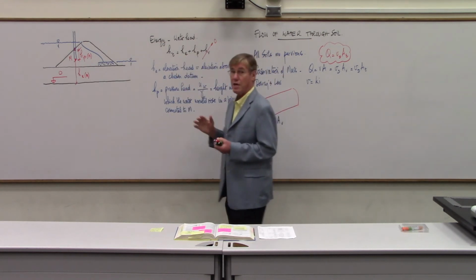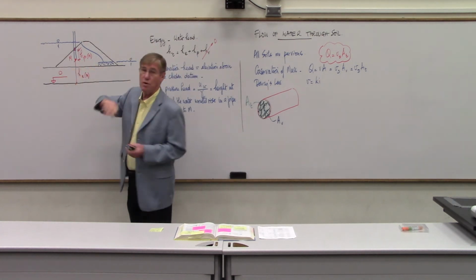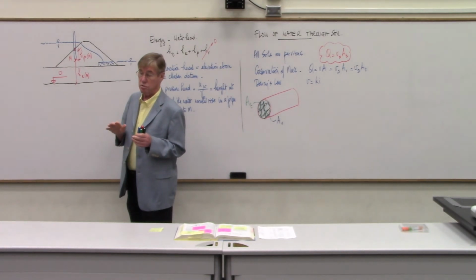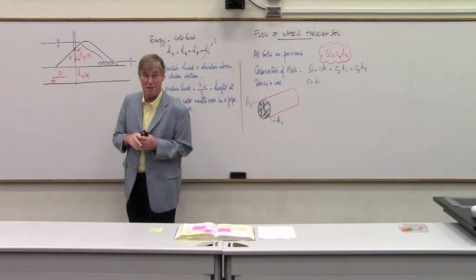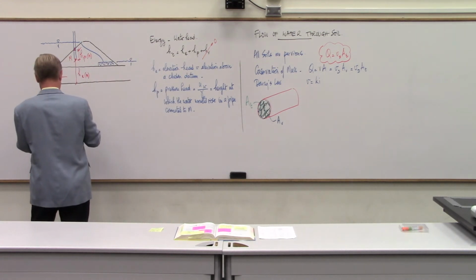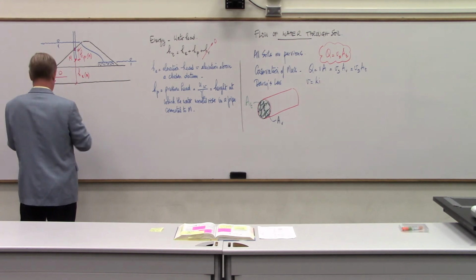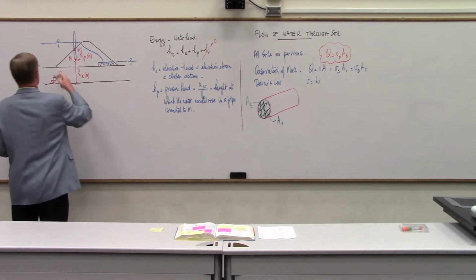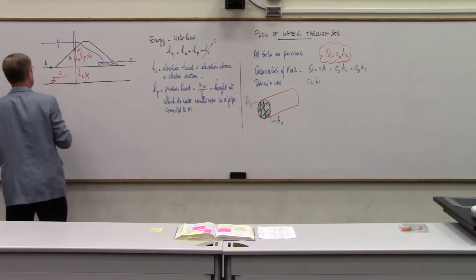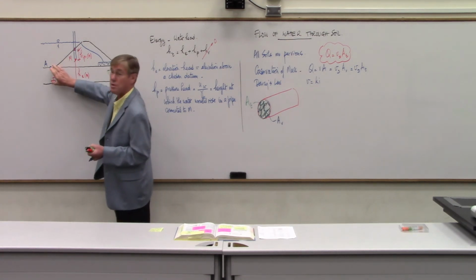And you might have guessed, if I had asked you, well, here's M, where does the water rise? You might say, oh, it's going to rise up to here. That's true if the water is not moving. If you're in a lake, so if I go here and I take a point A, right there. Okay, this is A. What is the elevation head at A? Well, height above datum, right?